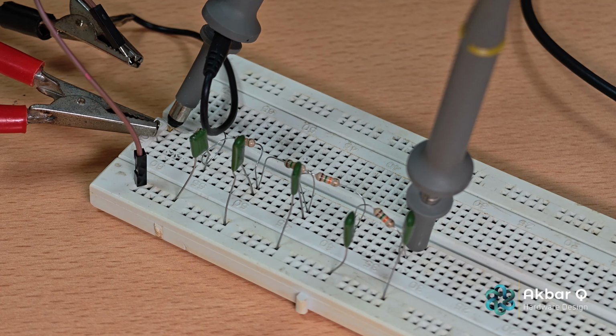So what kind of filter do we use? We use a low pass filter. A low pass filter's job is to allow low frequencies to pass and attenuate high frequencies. So in effect, the high frequency carrier gets attenuated significantly while the low frequency data is able to pass through without much attenuation. Now, one filter is not enough because one filter will cause only a small amount of attenuation in the carrier signal. The ideal scenario is a brick wall filter.